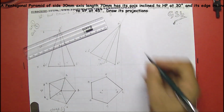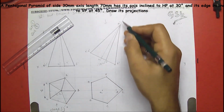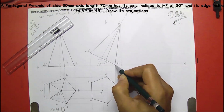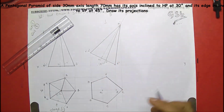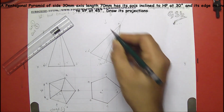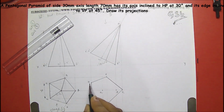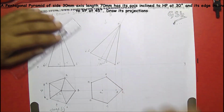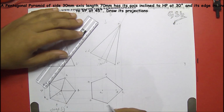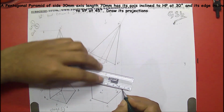Right, now coming to the inside, when you're looking in this direction, you can't see this bottom D, because that is under this portion. D can't be seen, so D can be in hidden form. And looking in this direction, you can see A dash O1 dash, B dash O1 dash means A and O1 you can see, B and O1 you can see. And coming to this one, C dash and E dash and O1 dash can be seen. Already E and O1 is seen, C and O1 is seen. Now I'll be joining the A and O1.